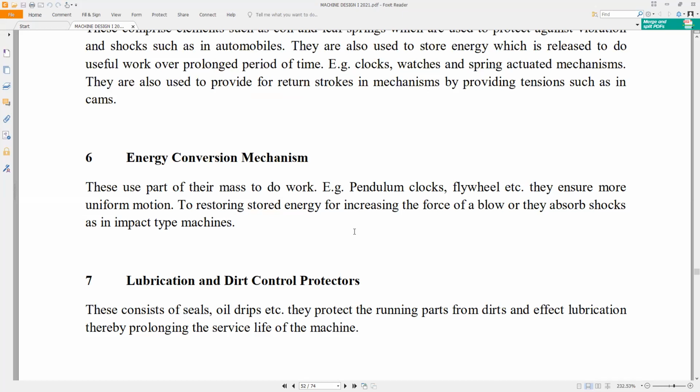It's an item that is having a flange on it. Okay, so one is on one of the shafts and the other one is on the other shaft. Then there are holes on the flange. So when you put them together, you can bolt the flanges together. Okay, so that will give you a very tight connection between the two shafts. You can only separate the shafts by removing the joint, by opening the bolts. Are you okay? So that's coupling.